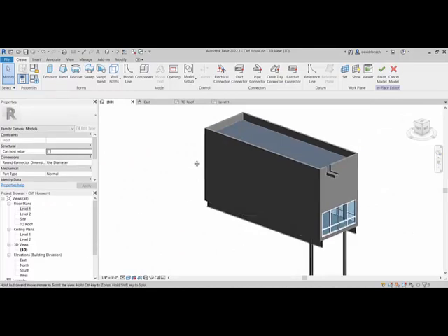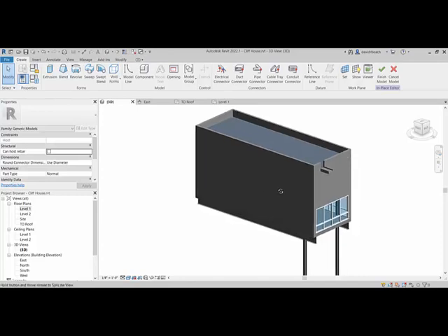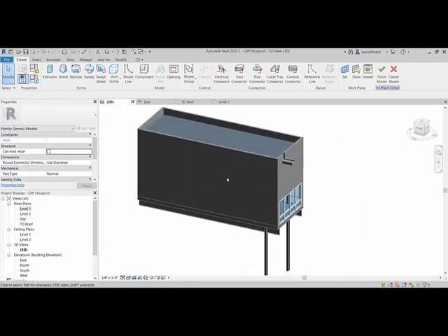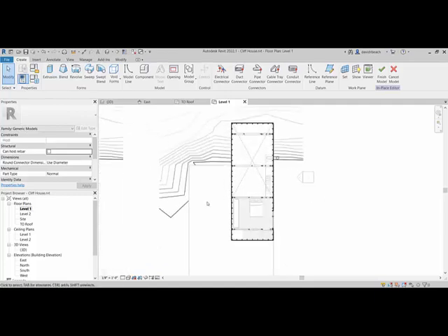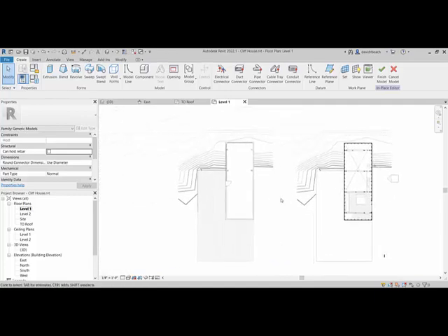So to do that, I think we're going to need to define a new reference plane, because if I use this wall as my reference plane, I really can't get that cylinder shape out and away from the wall, right? So I actually need a reference plane that's cutting through this direction.